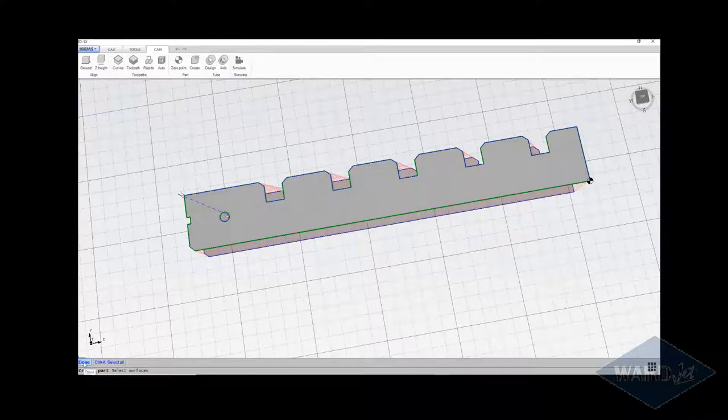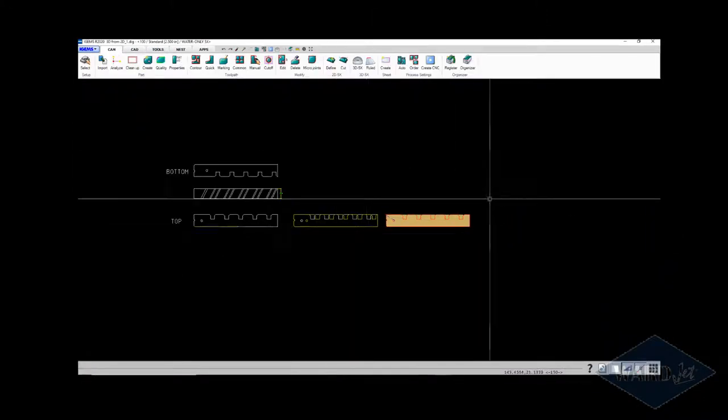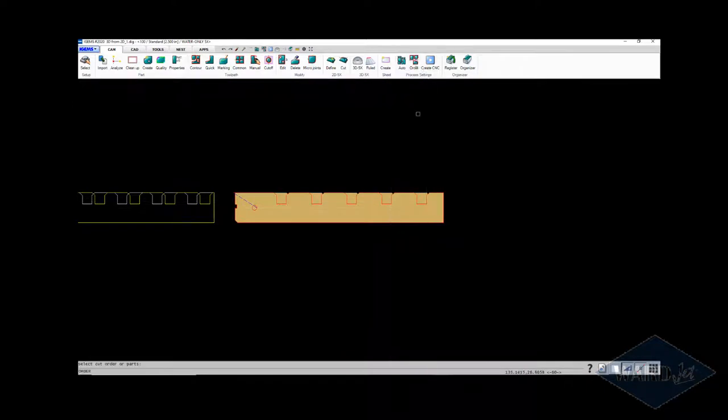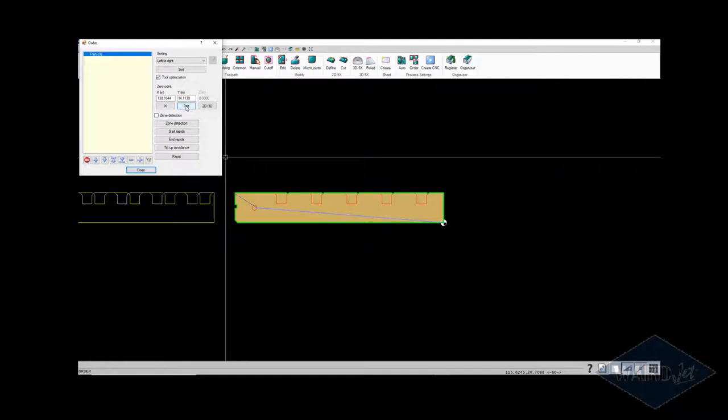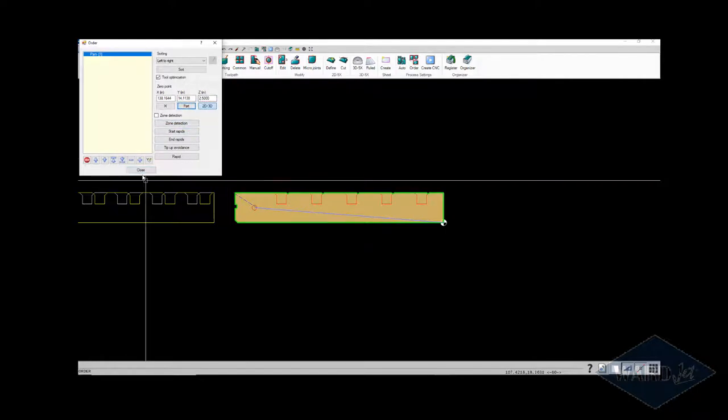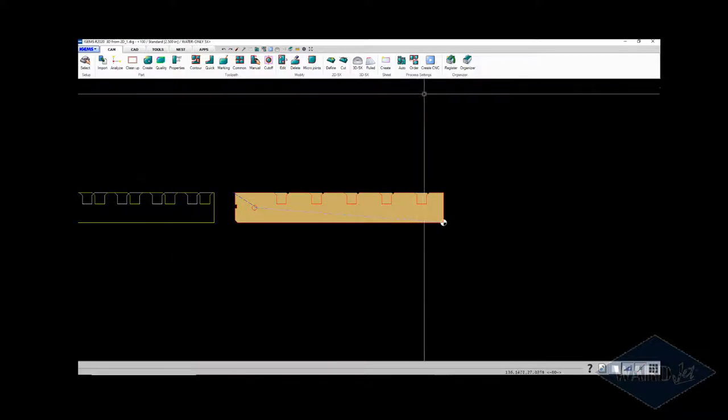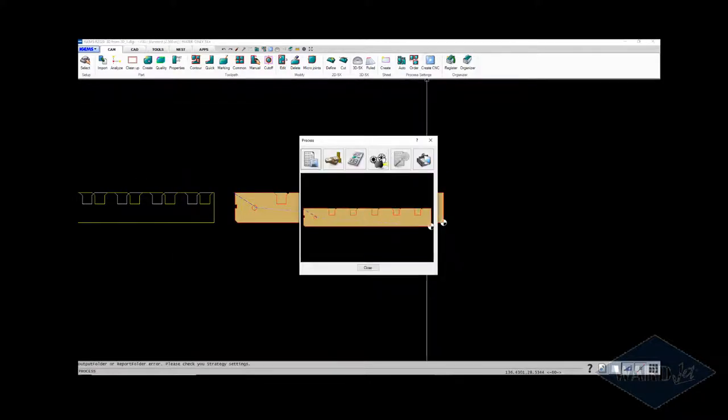Down at the bottom is going to prompt you to select surfaces. I'm just going to do Control A to select all, and then Done. And there's our part. So then we can set our 0 point, and always remember to click on the part button. Z matches our material thickness 2.5, so that's good. So now we can click on the CNC button and do our preview.